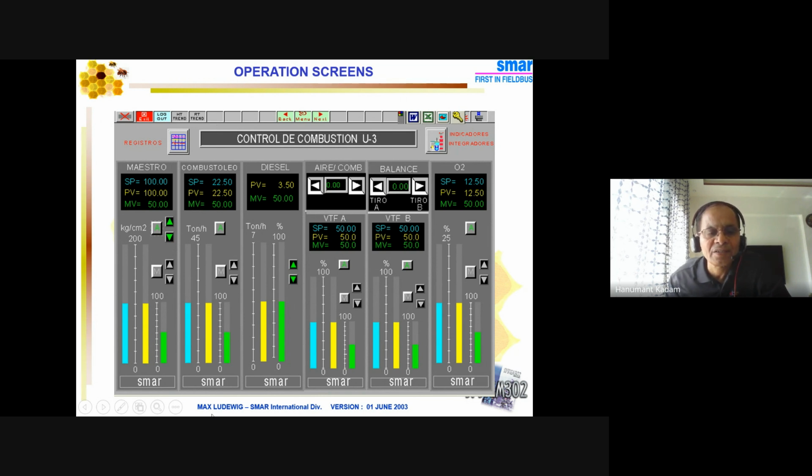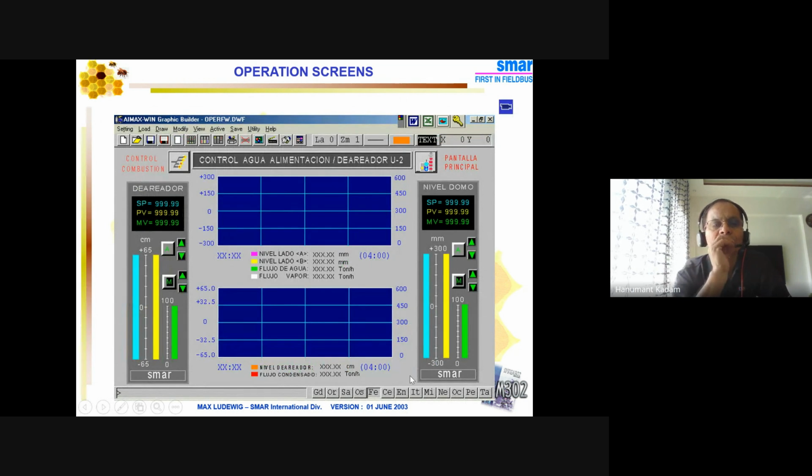Similarly, there is another bottom tab where you can see the alarms also. This is the trend display. For this particular section, you can see the previous last 8 hours how this parameter was operating, for your analysis or diagnostics. So that way you can see the trend of this here also.